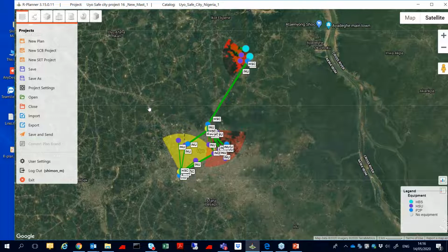But in case there are other vendors transmitting on the same tower, it is unavoidable to be interfered with. What we can do is to perform physical separation, 3 meters, 2 meters, from the other transmitting devices which are not synchronized to us.